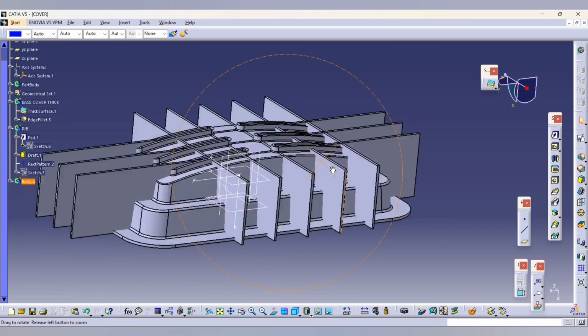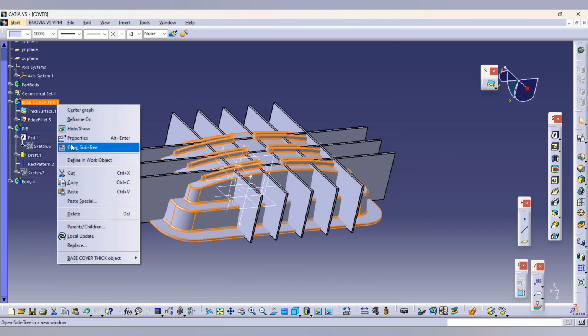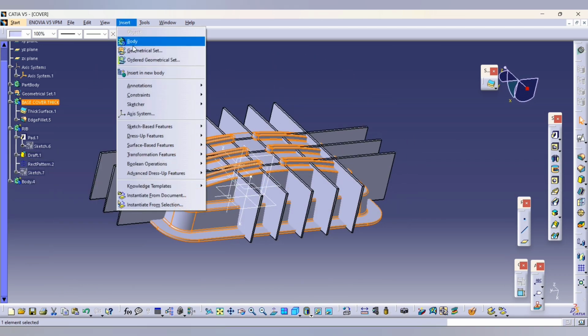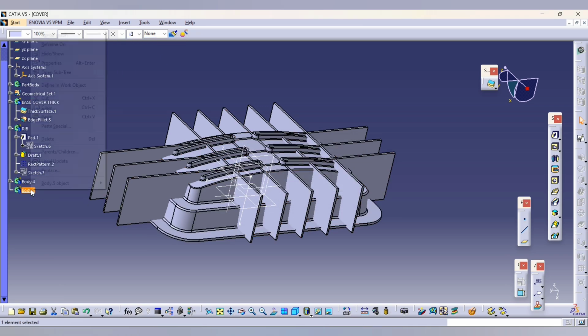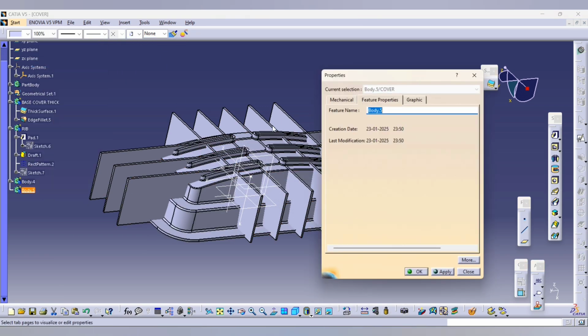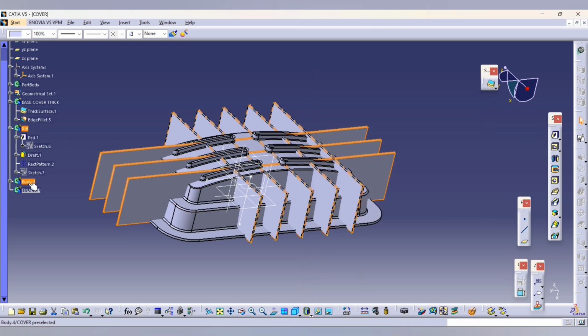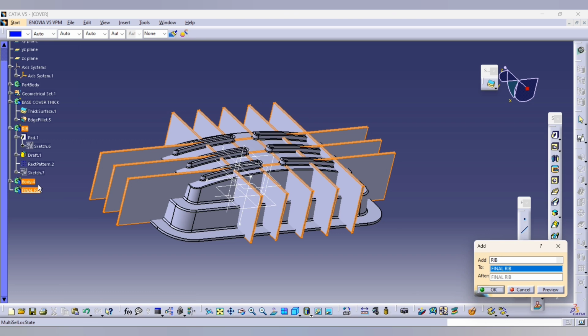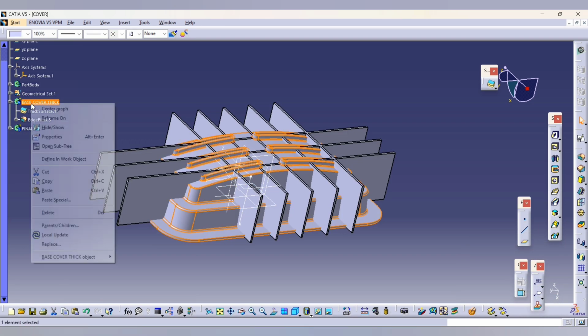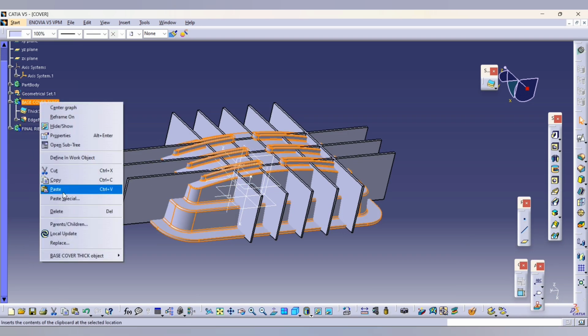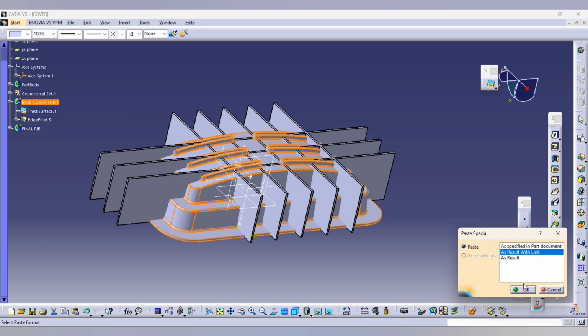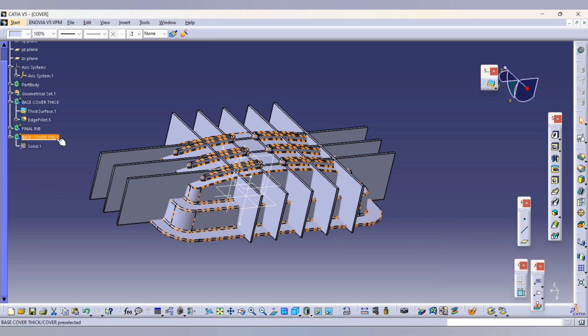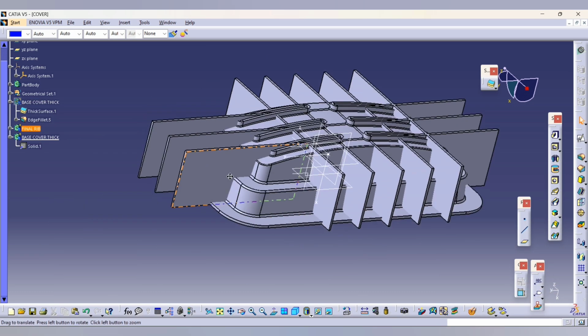so here the basic ribs are completed. Now the boolean operation is pending. First of all, we'll add both ribs into a single rib body. After that, we have to copy the base body, and copy paste as a result with link, and we'll add the positive thickness, whatever we require for the rib. So the base body gets height.